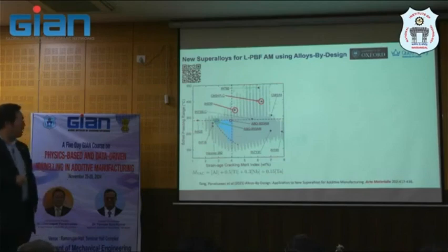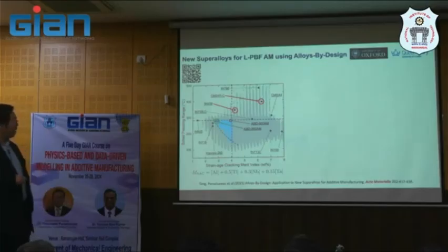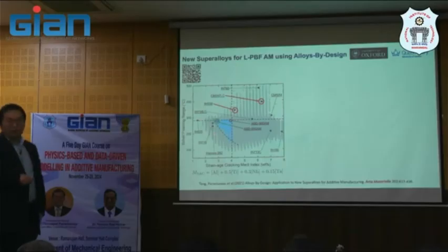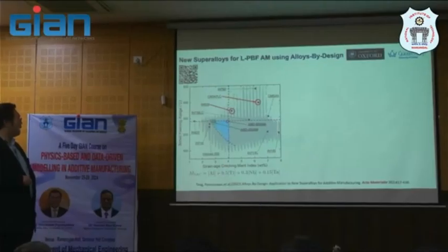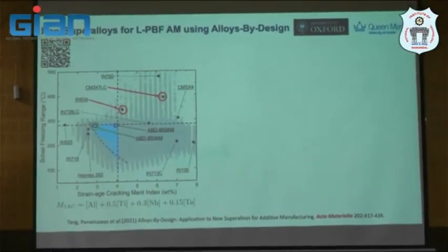Because you have a range for each element already for superalloy, you can get what we call the design space here, that you can look at in the gray dots, and you identify the range that you believe is a working condition for additive manufacturing, and then they draw this line and get the window of the freezing range.